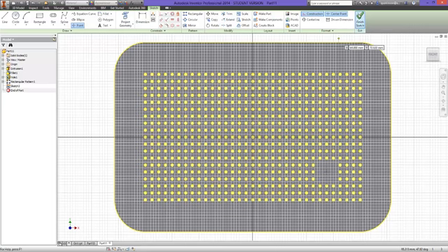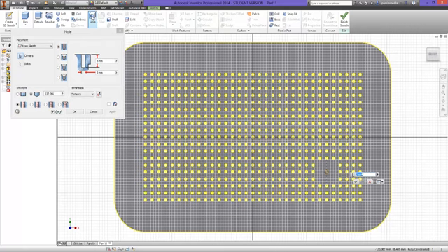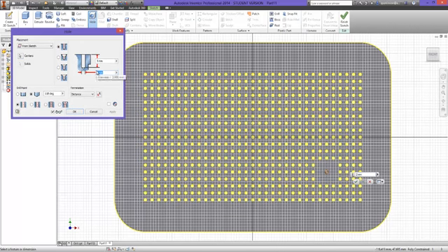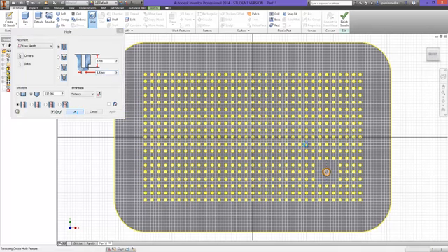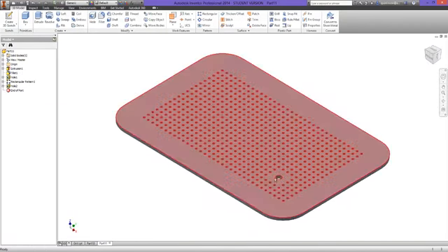There we go. And then I'll go to 3D model, hole, and it'll already put it in the right place because I've just put a point there, and just change the dimensions. I want that to be 5.5 millimeters, and I'll just press OK, and then I'll just home that. You can see that I've got the volume control, a nice space for it, and all the holes for the front of the grill, and that's the end of that component.